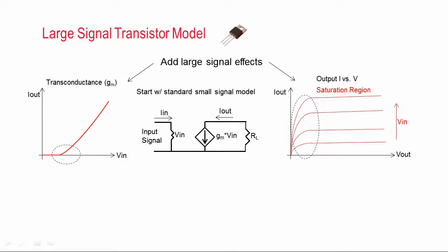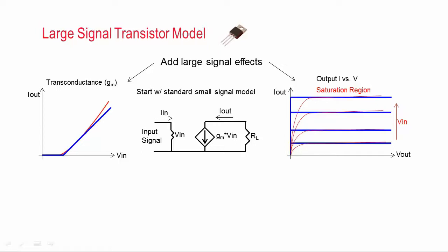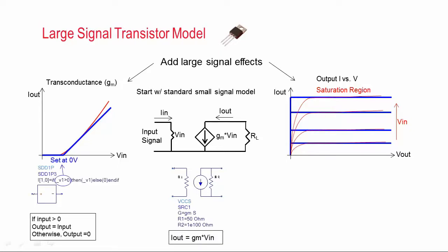But to realize the classical power amplifier waveforms, these regions really need to be idealized, which is part of the reason that it's so hard to achieve this ideal operation in practice. But it's pretty straightforward to implement these functions in the circuit simulator. So for the linear gain block, I used a voltage-controlled current source component, while for the nonlinear blocks I use components called symbolically defined devices. And these allow me to relate the input and output through an equation.